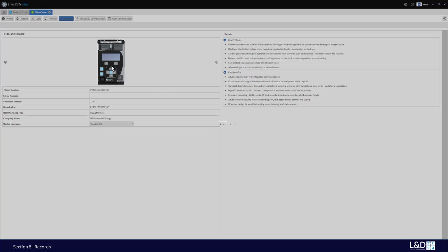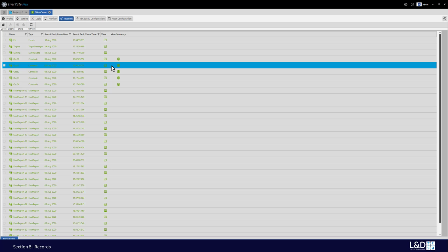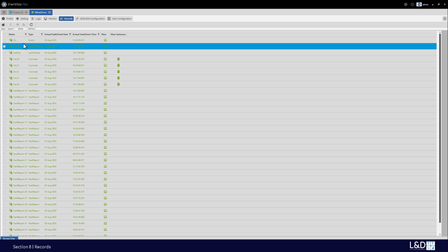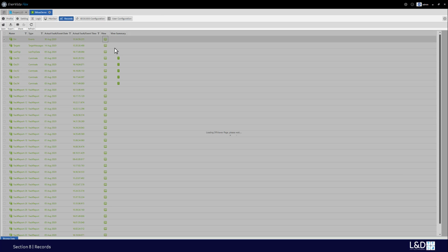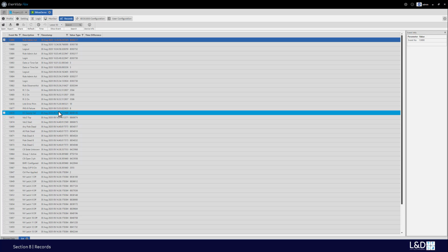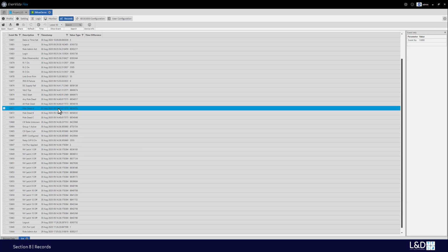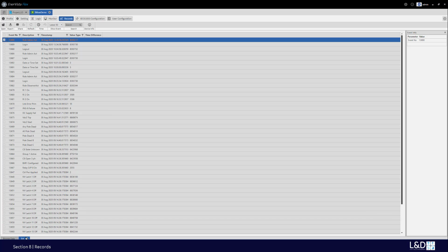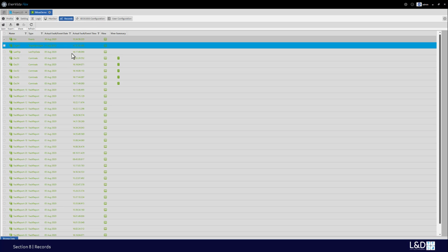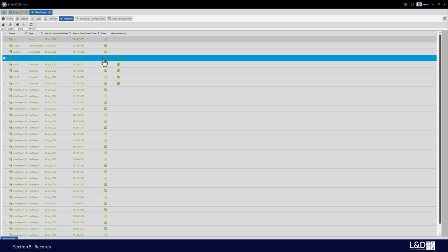We're going to open the records, for example, the events and oscillography. Okay, from here, we see the top one is the EVT, that's events. We can double click this view. We can see what events happened to this device. And we can close this events and open the COMTRADE. So we can first view the summary of this first COMTRADE.